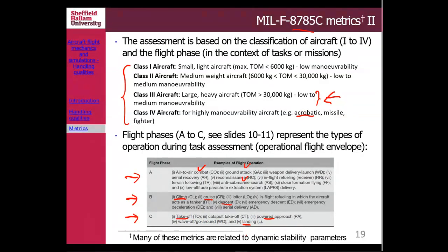In aircraft design, when we assess or design the aileron flight control surfaces, I recommend you look into flight phase C, the approach, because we want to assess the sensitivity of your flight control system during low speed.